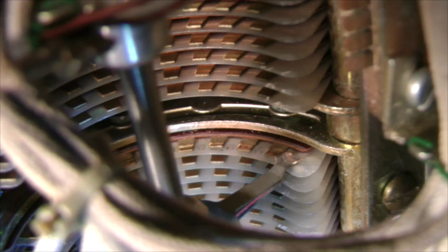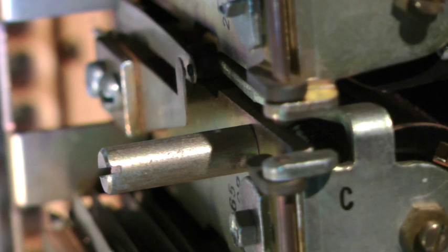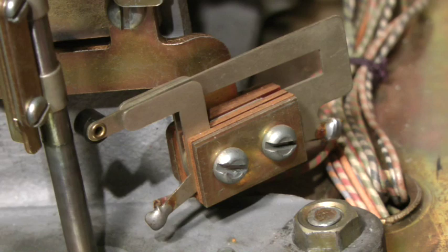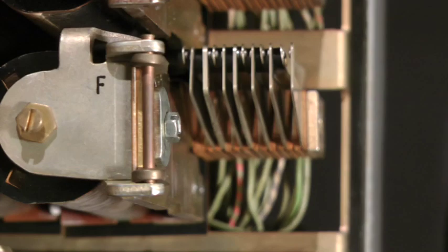The lack of battery on any sleeve terminal can be caused by a trouble condition, an abandoned call, or a CO technician performing line finder tests. The rotary step to the 11th position occurs in the same way as any other rotary step, up to and including the release of the C relay. However, as the 11th rotary step occurs, the cam on the line finder shaft strikes the 11th rotary step contact spring assembly, causing these springs to operate. This fully operates the F relay directly via its secondary winding.